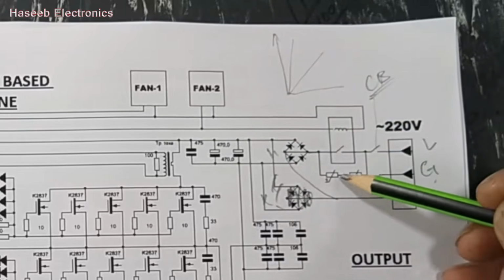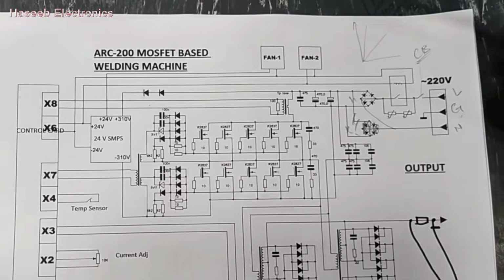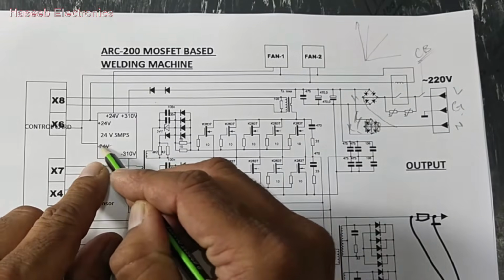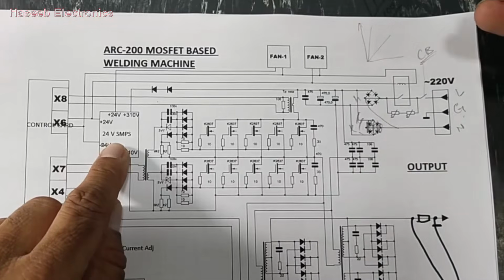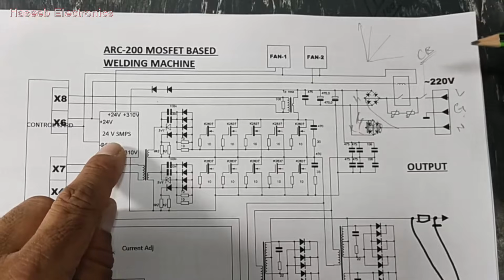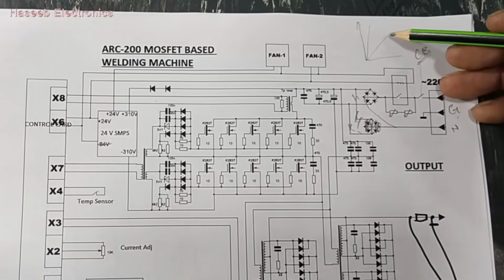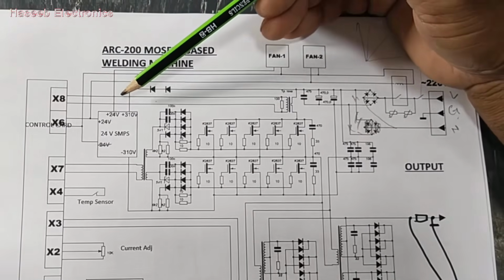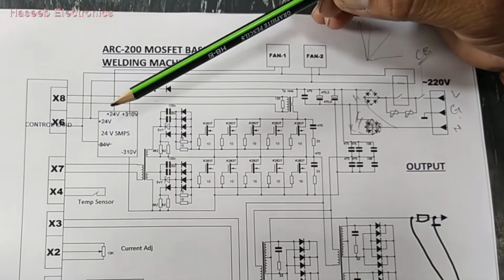When the current starts flowing and this capacitor charges up to a specific level, for example, our SMPS circuit has an IC with a soft start circuit, an IC that can sense the voltage, the minimum voltage, we can say 90 volt. Above 90 volt, this IC will start switching. When the voltage reaches 90 volt, this IC, this SMPS circuit, this power transformer will start to give output.